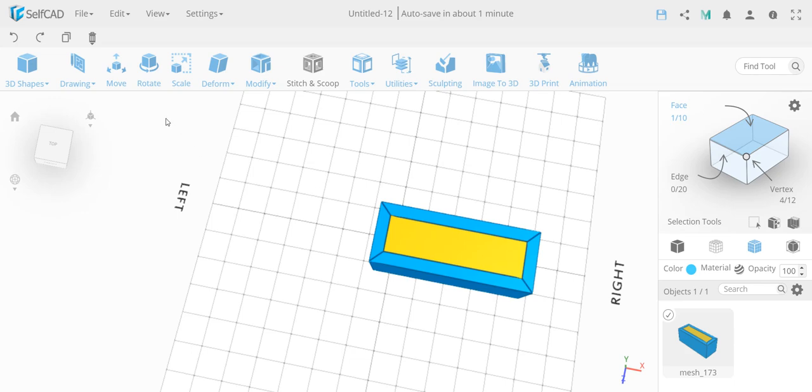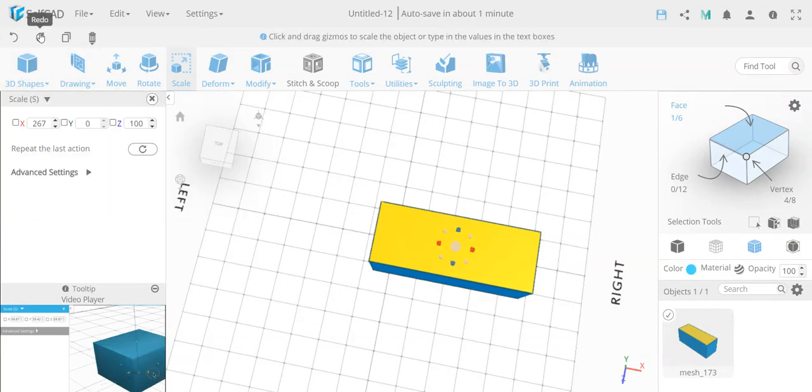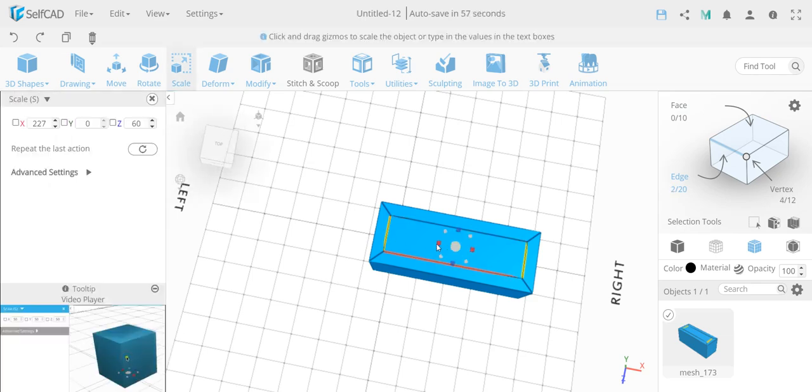But you can anytime scale the faces, and by the way, you don't necessarily have to scale the faces. You can also do the same thing selecting edges. So you can go to edge mode and select two edges. It will be the same idea as selecting faces, and you can scale these as well, enter values, and so on. So you can play a lot with moving the geometry, and yeah, so those should work.